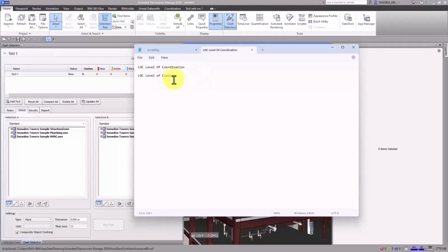After that, we need to define the level of the clash. As an instance, when we have a riser which goes through the floor, when you want to report it, you want to report it as a clash and describe it, or you want to ignore it. When you are controlling these small details, you're going to create a high level of clash. And in this way, for sure, the duration of your project will be longer, because creating the documents of the projects is really time consuming.